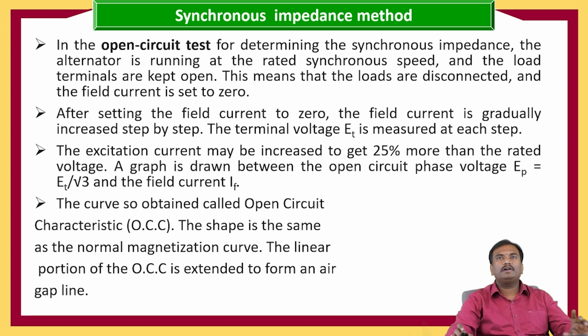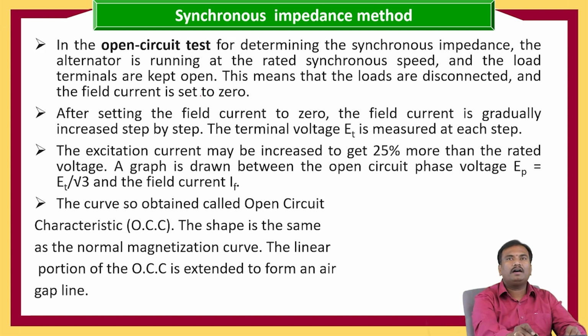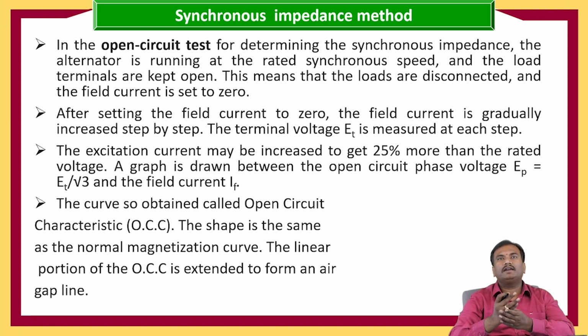The most important thing is that whatever mechanical input we are giving to the alternator, it should run at synchronous speed. And the load terminals are kept open. This means that the loads are disconnected and the field current is set to 0.